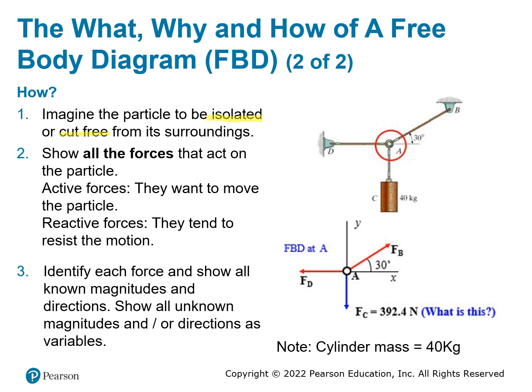So in this case, when we focus on the point A, we're going to cut off this cable and this cable and this cable. Let me just use different colors so you can see where we cut. We cut this one, we cut this one, we cut this one. And whenever you cut off something, Newton's third law tells us that you're going to have a reaction force. So when you cut something connected to the object, you always have a force.